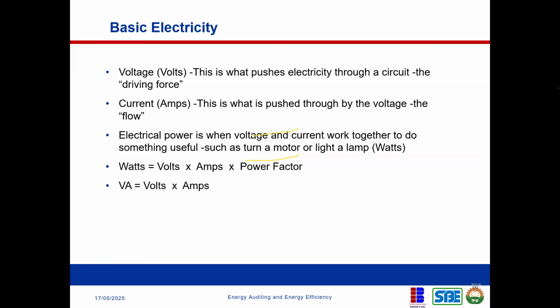That is the current. A lot of times people say you have low current. It's very common, especially when you have a transformer that is far from your house. By the time the pressure, that is the voltage, gets to your end, the voltage will reduce. So you're not really saying you have low current. Essentially what you have is low voltage, not necessarily low current. But that aside, I hope with this simple analogy, we understand what voltage and current are.